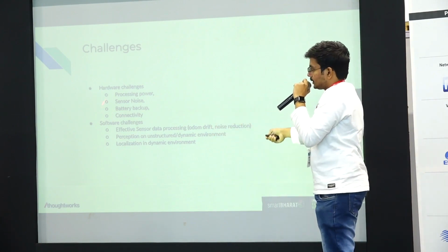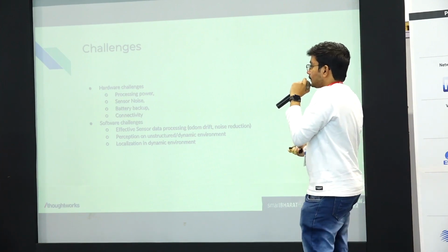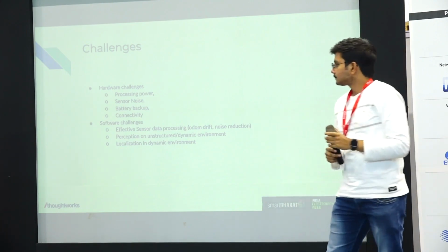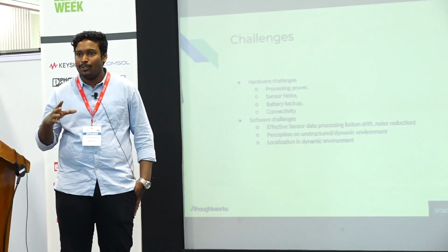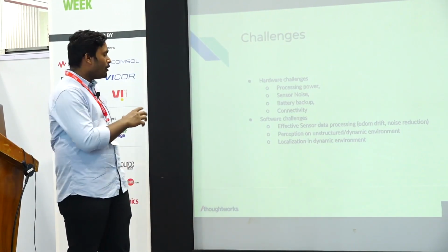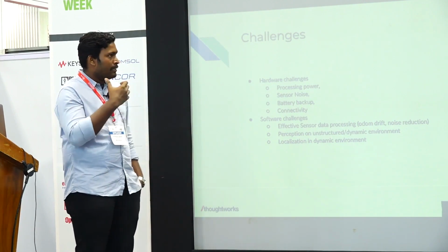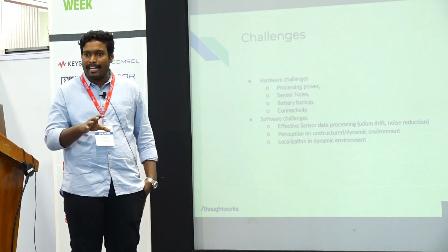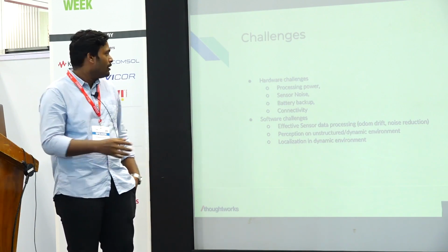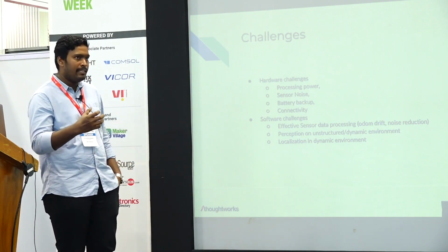And sensor noise, yeah, because there are multiple sensors, we need to make sure that we don't have noise and errors because of it. And battery backup, connectivity, and the software challenges. And actually, sensor noise is dependent. If you use quality sensors and quality algorithms to fuse the data, it's not going to really affect you. But it also depends, because the connections and the environment can add some noise to the data. So your algorithm has to be very dynamic and effective to understand the data and fuse it, so that you can actually use it.